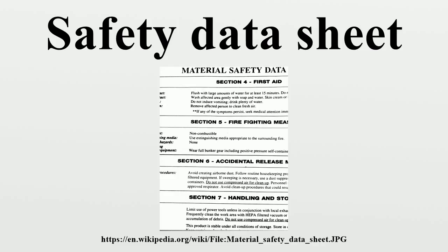Reviews of material safety data sheets by the U.S. Chemical Safety and Hazard Investigation Board have detected dangerous deficiencies. The board's combustible dust hazard study analyzed 140 data sheets of substances capable of producing combustible dusts. None of the SDSs contained all the information the board said was needed to work with the material safely, and 41% failed to even mention that the substance was combustible.